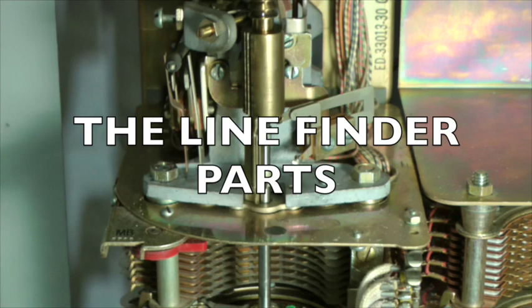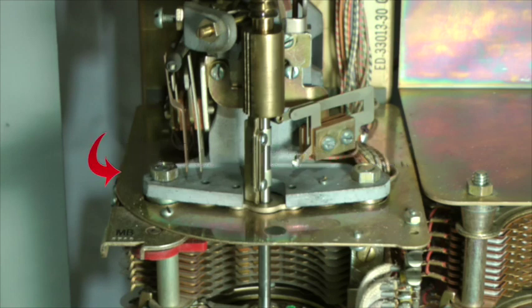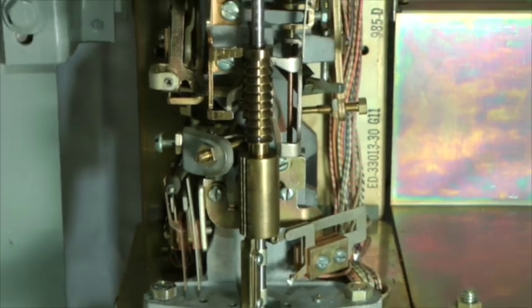Now I'll provide an overview of all the line finder parts. The 3 main structural parts of the switch are the switch base, the switch cover plate, and the switch frame. The horizontal bottom plate is called the cover plate, which attaches to the switch frame near its front and to the switch base at its rear. It provides support for the test jack assembly and the make busy switch, and acts as the bottom dust and protection cover. The thick gray cast iron switch frame provides the mounting support structure for most of the apparatus on the switch, except for the relays.